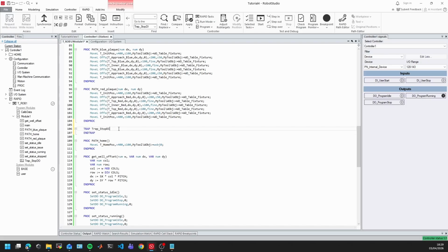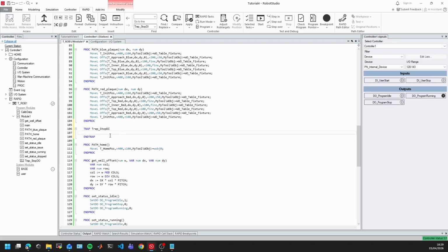As you can see, it doesn't allow us to bring any parameters, so there are no parameters in here. So the only thing that I can do is small pieces of code. Try to make it as fast as possible, because you don't want to waste time in these callback functions, because remember, it's going to stop the program, go there, do something, and then go back to the program.